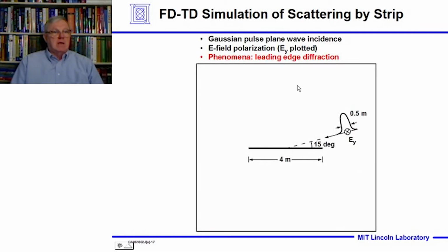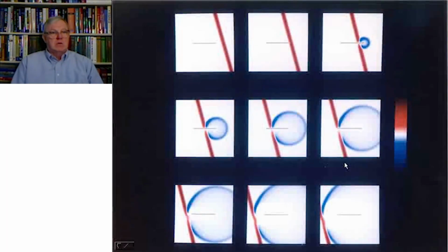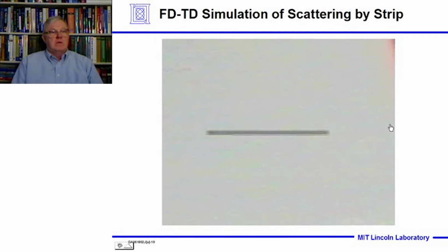Now we're going to look at leading edge diffraction, where the beam comes in and will hit this leading edge and will generate a backscatter at this leading edge. And you can see the beam coming in, hits it, and creates. And also you have the reflected beam up here too, as you'd expect as it hits. Okay? But coming in the direction of where you were, you'd have the radar back up here. This is the leading edge diffraction that will come back to you.